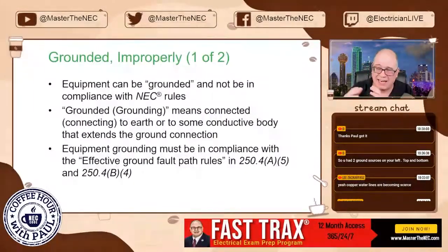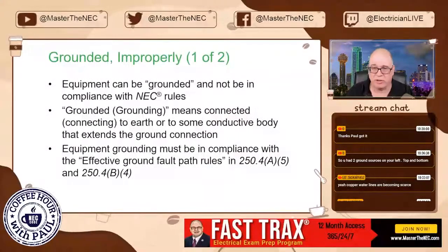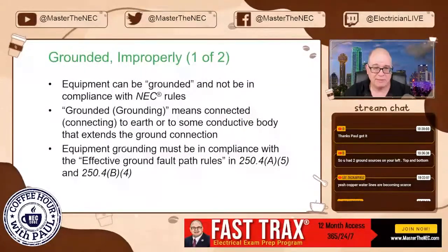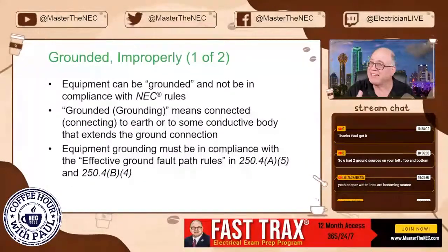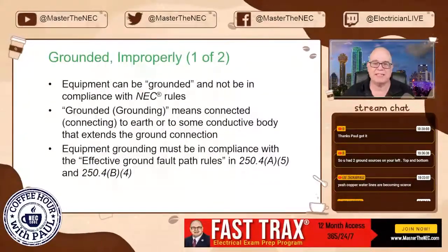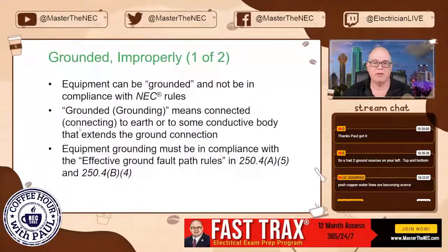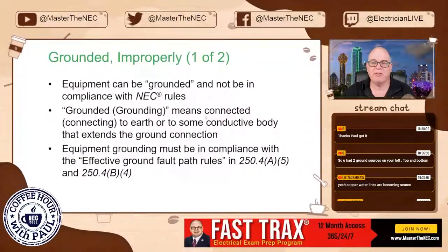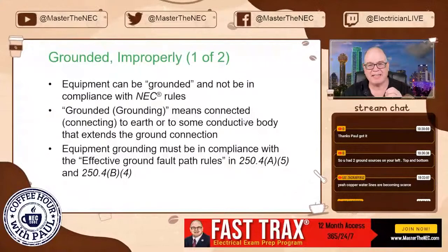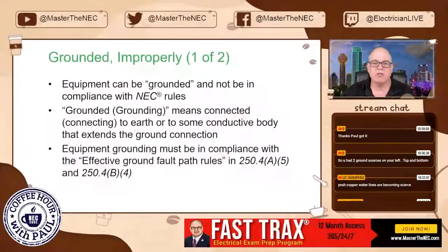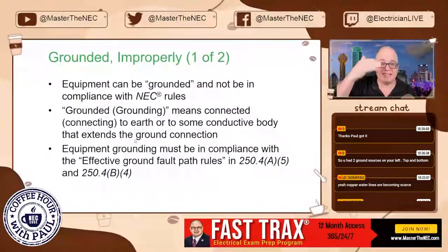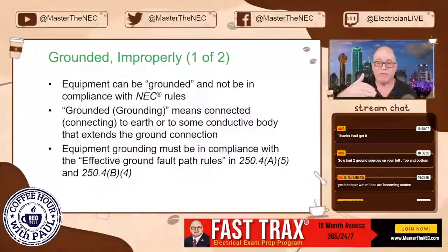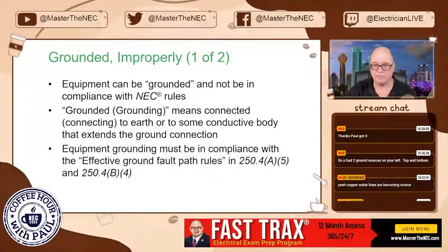Driving a ground rod at a light pole is never going to clear an overcurrent device, ever, okay? So something can be grounded, but it's not done so in accordance with the NEC, which again is a safety standard. Grounding means connected or connecting to earth or to some conductive body that extends that connection to earth. So an equipment grounding conductor is extending that connection, okay?